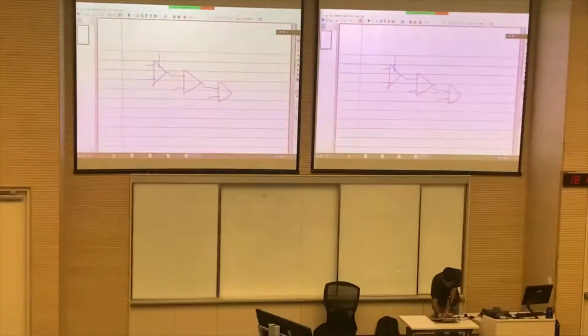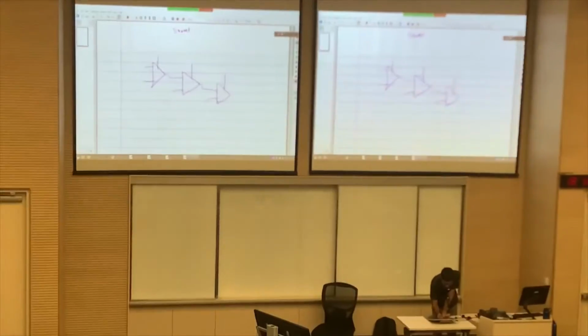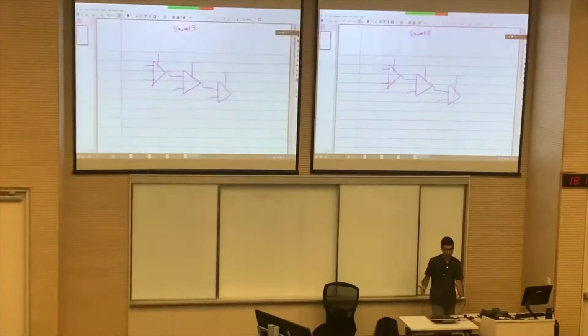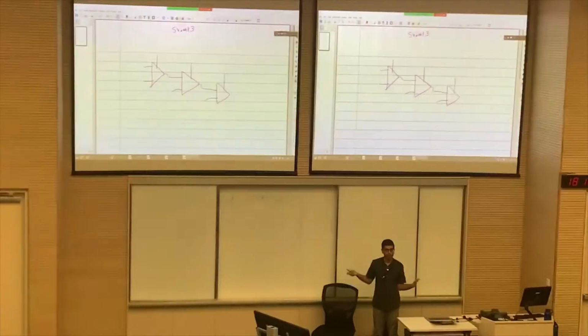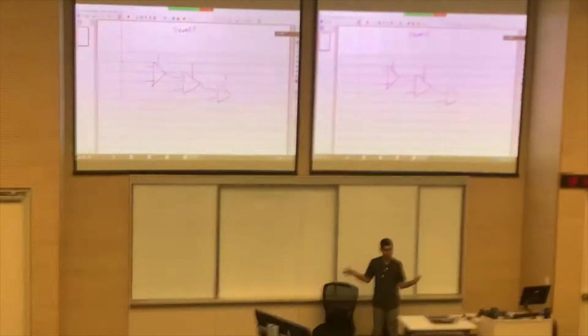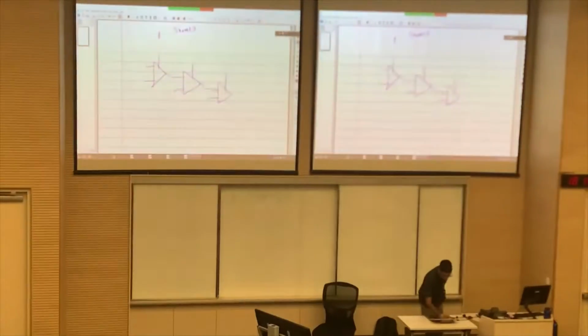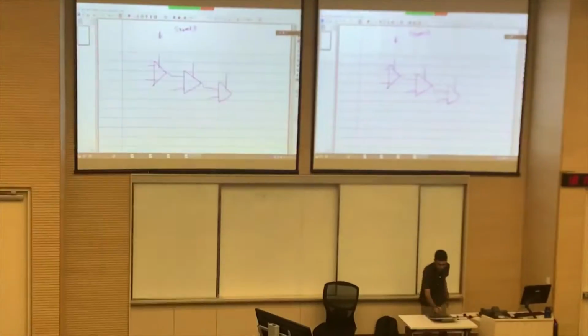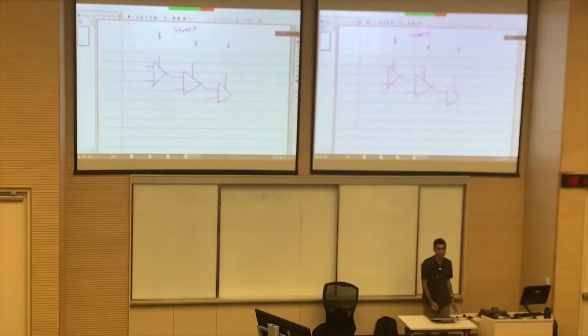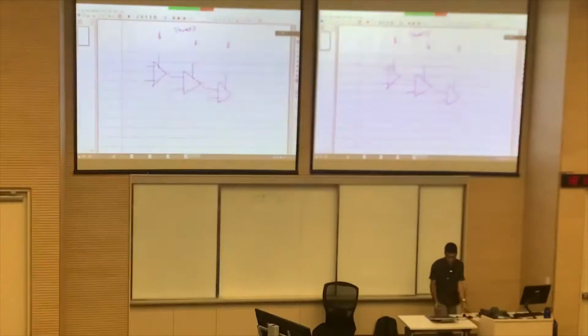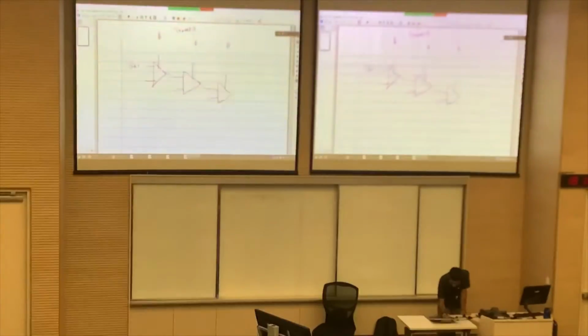It will be connected like this, and here it will be some variant of this. And let's say the amount of rotation is SHAMT3, because it's going to be a 3-bit rotate. Because a meaningful number of bits of rotate is 0 to 7 for an 8-bit value, right? So this will be for rotation by an amount of 4. This will be for a rotation by 2 and a rotation by 1. That's the idea. So let's say SH in is the input.